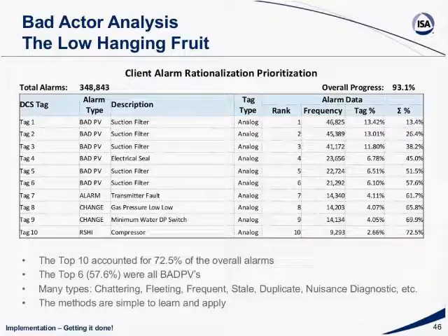What was interesting is that a lot of these were associated with pumps. The reason these bad PVs were coming in is that the pumps were off, and they were supposed to be off. There was nothing wrong with the system, except they had the zero set to exactly 0, and they were getting a little chattering. Instead of exactly 4 milliamps, the signal was going like 4.05, 3.95. As it chattered just below the 4 milliamps, we got a bad PV alarm.